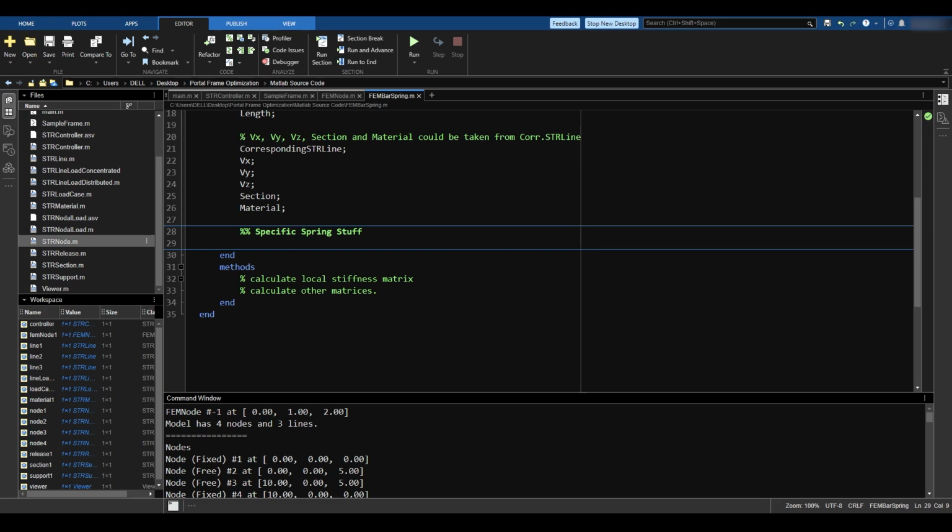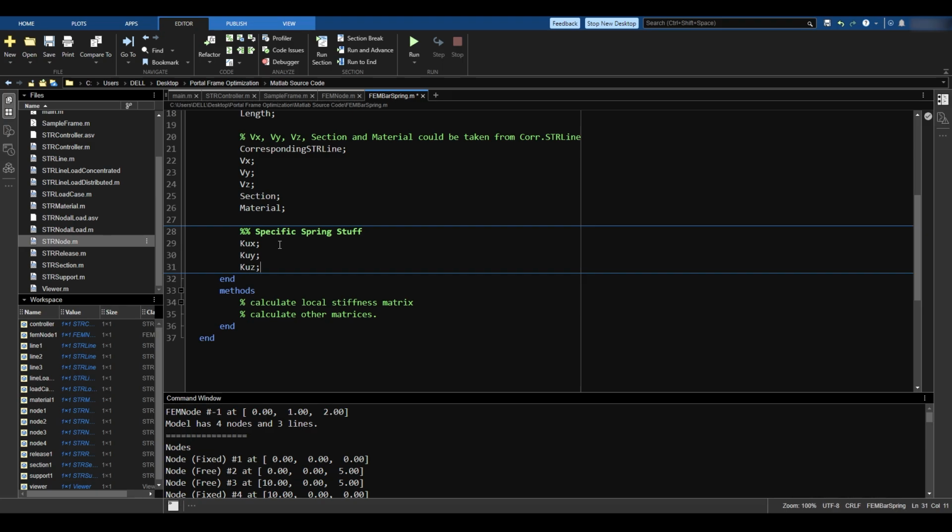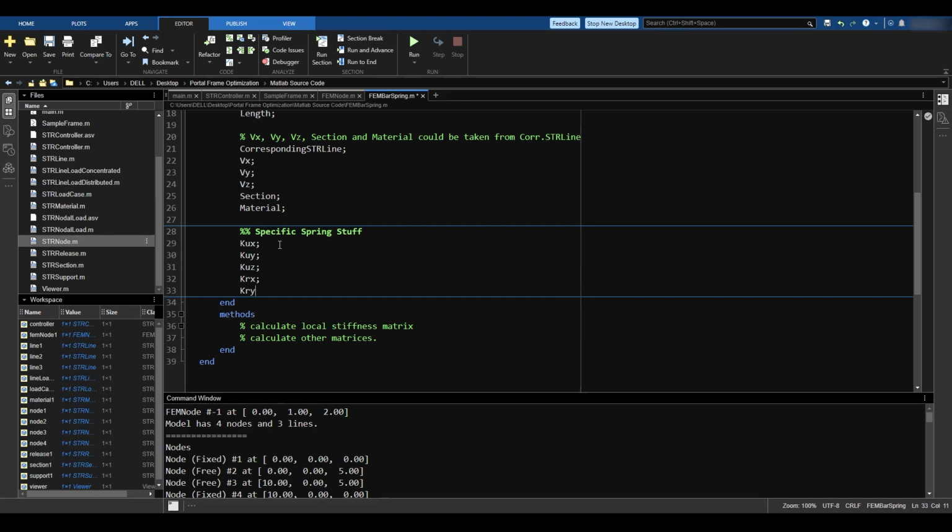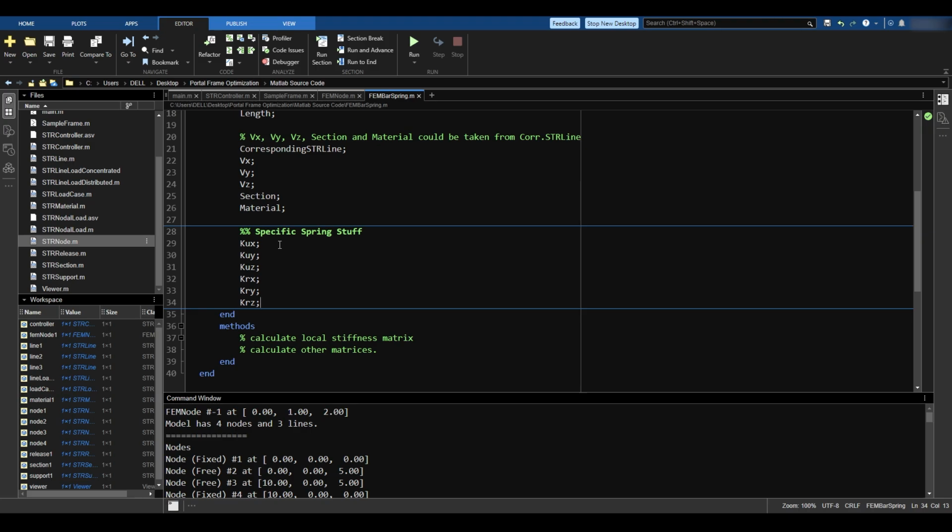I'm just going to go specific spring stuff. So let's add our specific spring stuff. Now a spring, well, the only thing that kind of makes a spring special is its spring constants. So here, I'm going to add me a KUX, KUY, KUZ, and you know the drill, KRX, KRY, and KRZ. I'm not going to make a start and end because I will assume the start and end have the same spring stiffnesses. And those are the things that the spring needs. Now in the methods of what the spring can do, this is going to be filled with tons of code, but that's going to come for later.